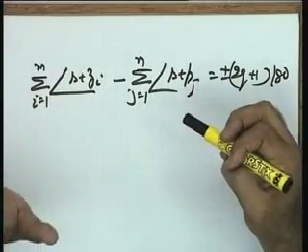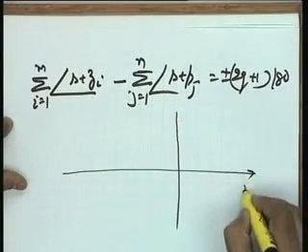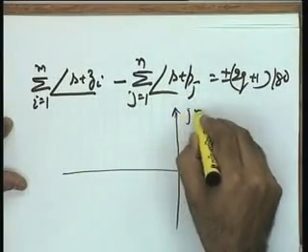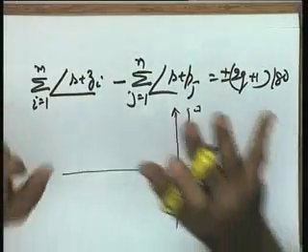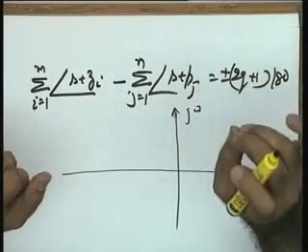If this is clear to you, then you have to answer my questions, please. You just keep the two conditions in mind, the magnitude condition and the angle condition. My question to you is this, that you scan through the entire S plane and tell me for what points on the S plane is the magnitude condition satisfied.